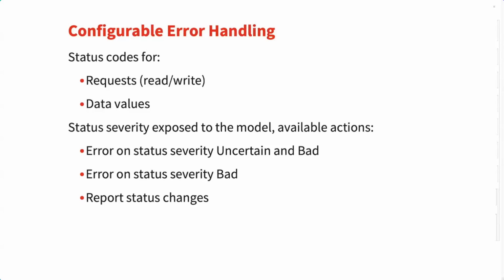Maybe the bad value isn't that important to our operation, or we can shift to a different operation mode to remedy the situation. To aid in the decision making, the blocks will also come with a timestamp output, so that it is possible to take different actions depending on how long the value has had that particular status code. Selecting to only report status changes will also mean that the simulation will automatically reconnect to the server in case the connection goes down due to network issues.